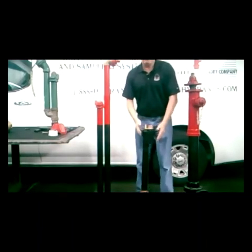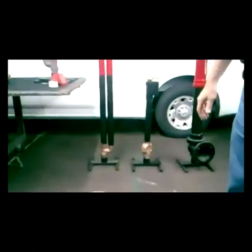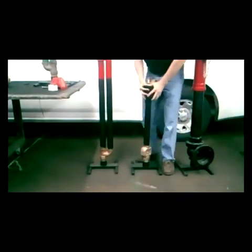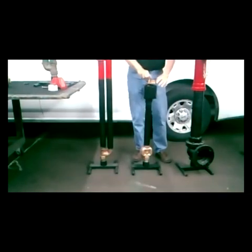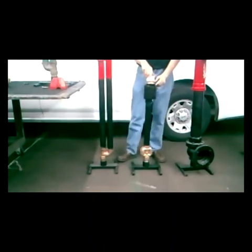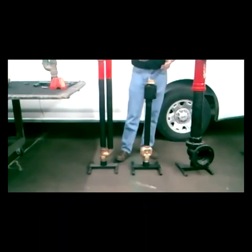This is the TF500 that fits in that 5.25-inch valve box. The one that goes into that homemade assembly, okay? So again, I have the 2-channel valve with the weep hole down here. My operating nut is here. I have the cap that goes on to keep it clean while it's underground. When I come to flush the hydrant, I take the cap off, I attach my riser, I turn my operating nut, and I flush the line like we saw in that picture.